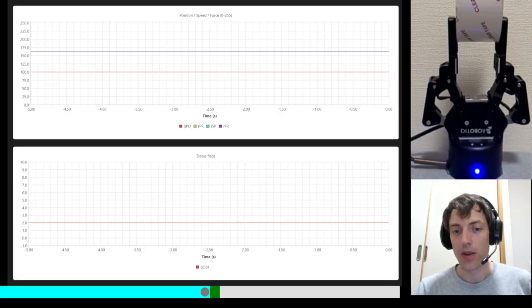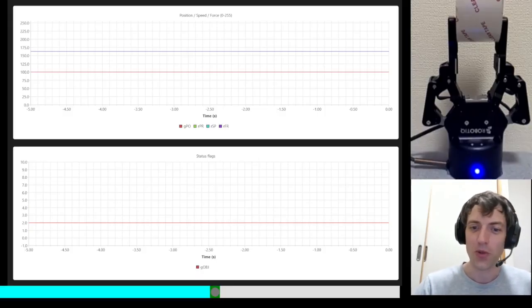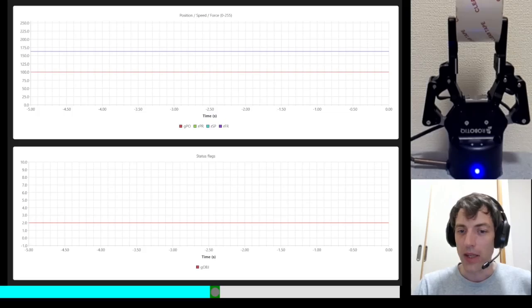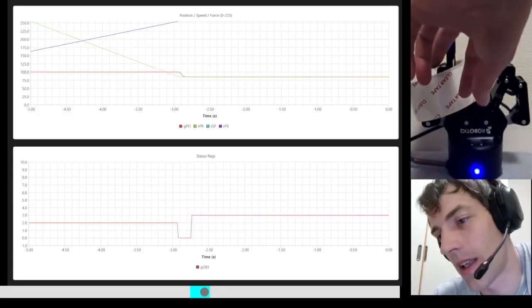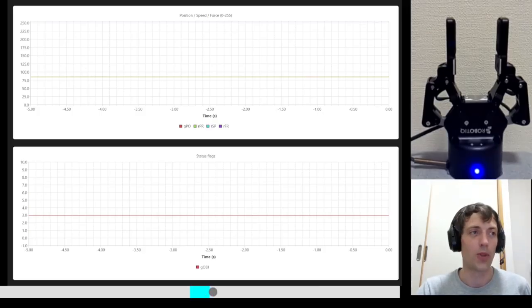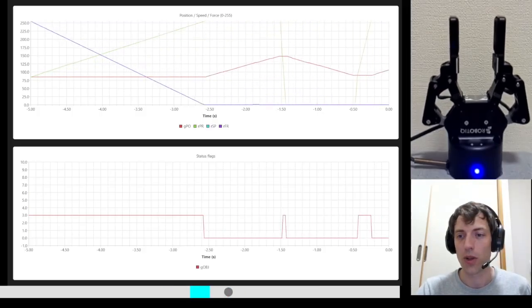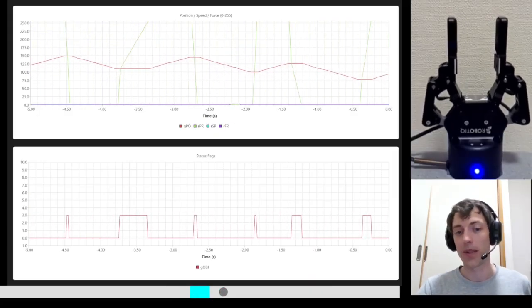So it's now in the force control deactivated mode. To go out of the force control mode, I go in the green zone, the activation zone. So now I am in the force control activated mode. I don't push it further, I don't reset the speed, and I go back to the center zone. This brings me back to the free move mode, so I can now control the speed of the gripper rather than the grip force. And so the object has been released.